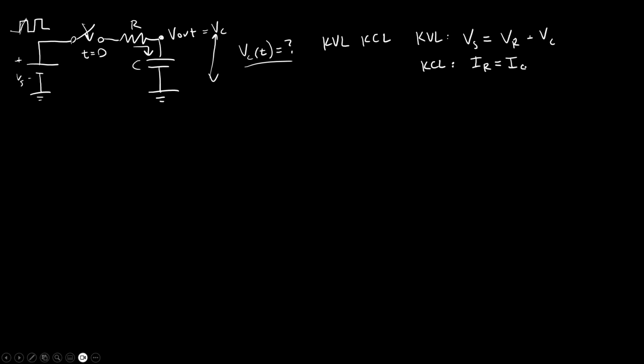Now, if I remember what we did on the previous slide, I had that differential equation I'm going to write with a different form now. Instead of x, I'm going to write it in the output variable that I want: tau times dVc/dt plus Vc(t) equals k f(t), where f is some, in this case, step function, and k is a constant.